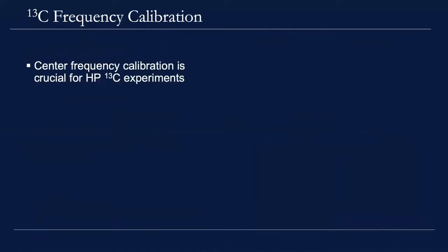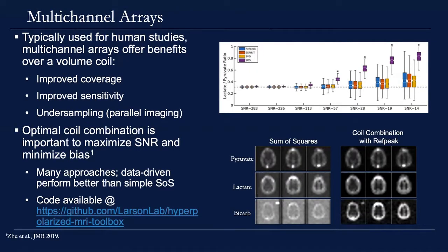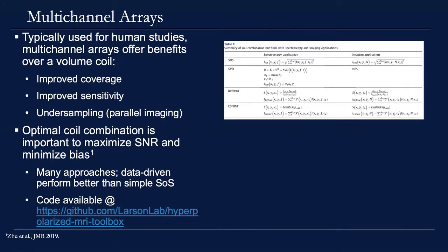So now that we have our coils, we need to get our, yeah. Is this, let's say, the comparison, does it also affect how many elements you have in the coil? So one algorithm, maybe it's better, let's say if you have 16, but the other maybe it's better for the 32, or between sort of the different eSPIRiT. Yeah. So I found that for those, they all perform pretty well. As you have more and more elements, I think you see more and more of a difference between the sum of squares and the data-driven approaches.